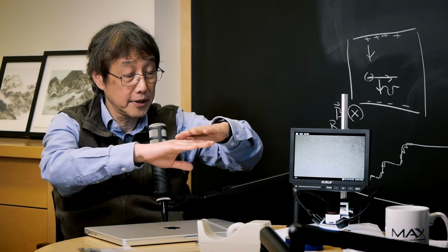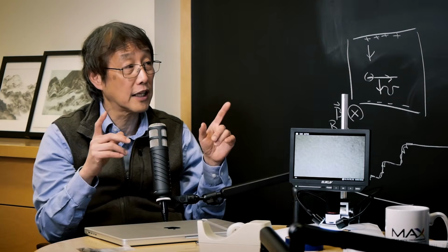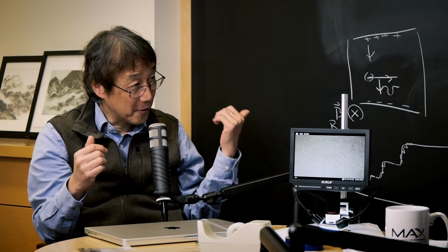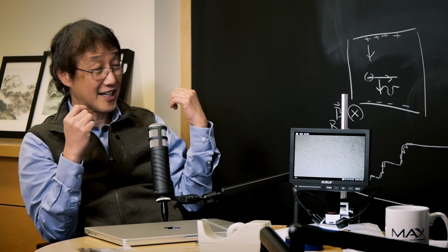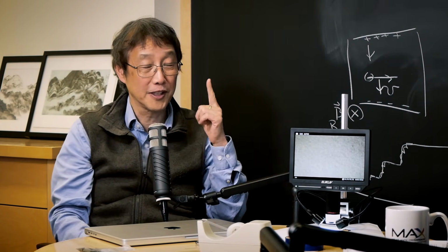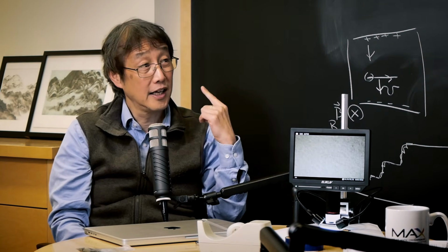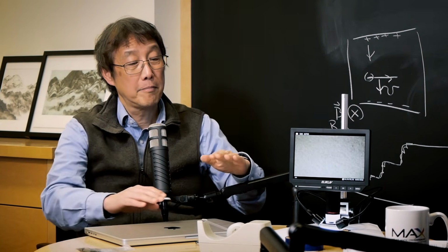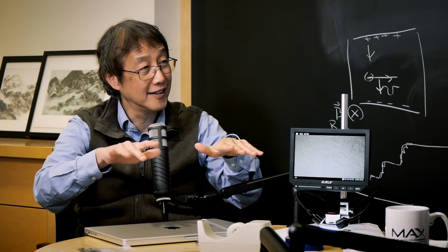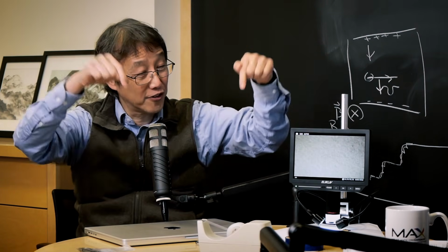I'm really curious. How do you do the gating or the wiring of these multilayer systems? Must be a big challenge. Yes. So the idea is you have to put these samples... I think this comes with another thing. Continuous films cover everywhere, but here it's a flake. So for the flake, we are still using Scotch tape to make the flake. It sounds very low tech, but it has a great advantage. First of all, it gives you really high quality single crystals that can be used in the device. Second, by choosing the right shape and right size of flake, you can expose different parts of the layers that you can address from the top.